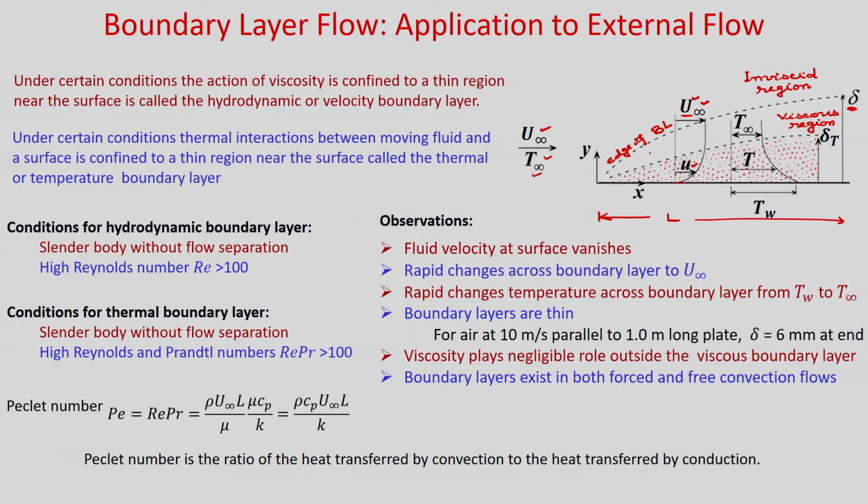So, inside this edge of the boundary layer there is a viscous region, and outside it is the inviscid region. You can see that under certain conditions the action of viscosity is confined to a thin region near the surface, called the hydrodynamic or velocity boundary layer.